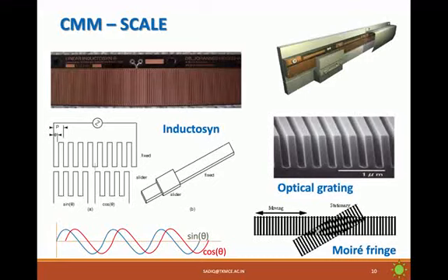For every movement, this pattern will be different. It is said that in optical grating, if 1/25 is the width between the gratings, such gratings will provide around 40 identifiable patterns in 1/25. That is, 1/25 into 1/40 is the minimum resolution. That is around 1/1000, that is equal to 1 micron, is the resolution that is seen.